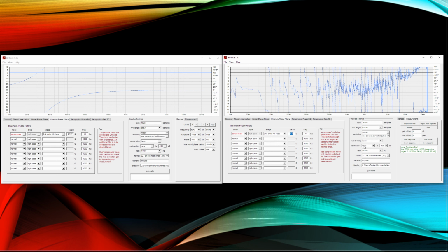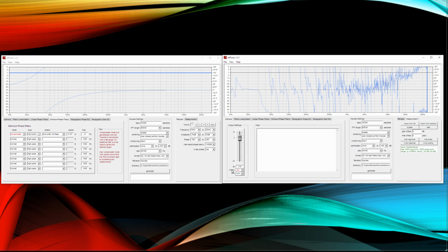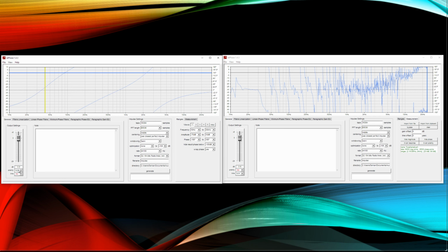and I could just create a convolution file with these settings. So this is one more trick. Also here, remember that we had to invert the polarity. So after creating, for example, this filter and another one, first order at 260, let's keep them normal for now, and another one, second order at 2700, all these three, even ideally this should be 0.6, and time invert them and polarity invert them.